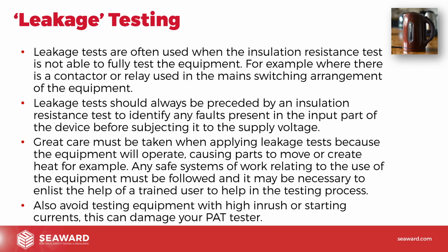So for us to fully test a piece of equipment like that, just doing an insulation resistance test only tests so far. In that case, we might want to apply a leakage test as well to fully test that equipment past the input stage of the power supply and actually get the full picture of it.